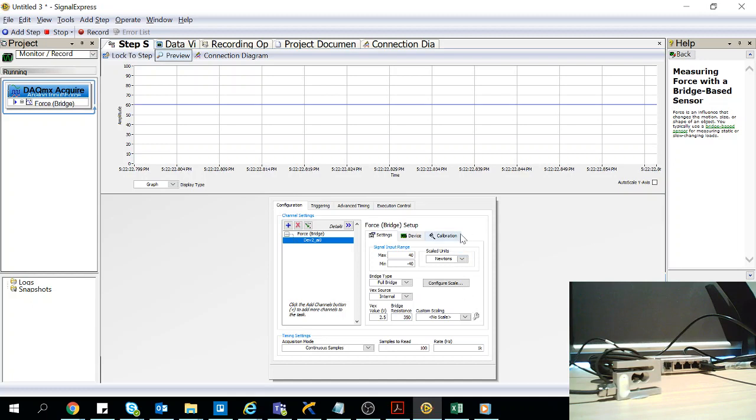And then the second thing is that the scale unit, I can also turn it into other default scales. Say for example, if I make it kilogram force, it will automatically adapt whatever is in the configured scale to kilograms from Newtons. So you can see now the value has dropped from 60 newtons to roughly about 6 kg.